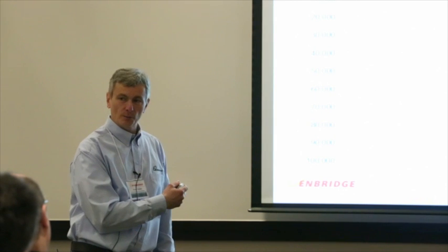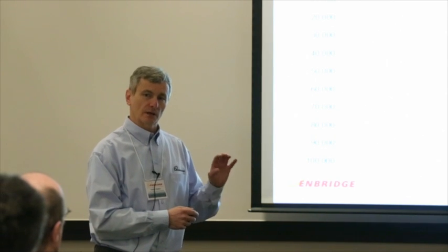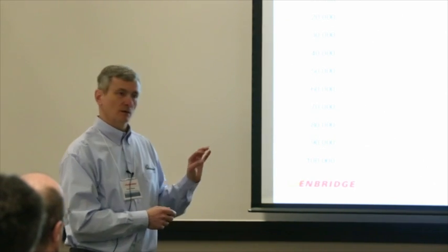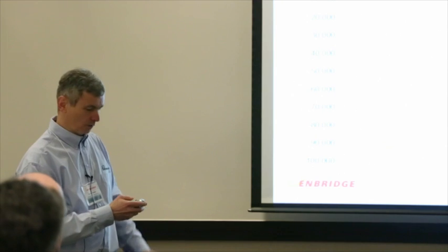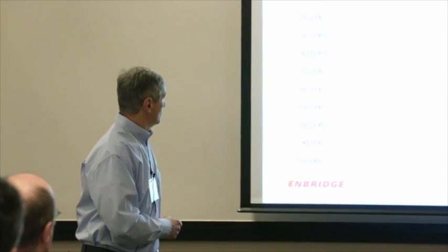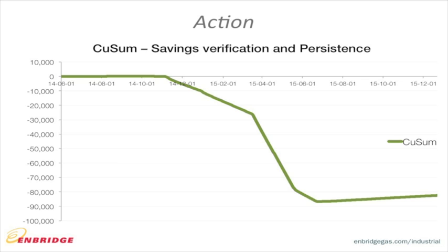So now the Cusum, we go back to this Cusum thing. Because we cannot tell by naked eye whether we're up or down on the target, especially over that period of time, what we need is something to tell us when we're getting off the target. This is what the Cusum is, that sum of those variances. You can see that here, it's baseline period. Then we go into the stable run.